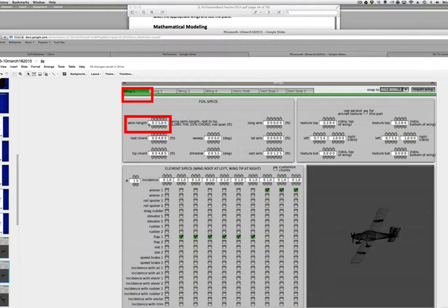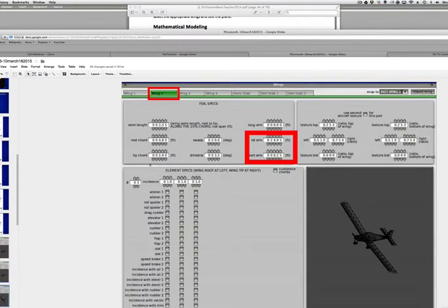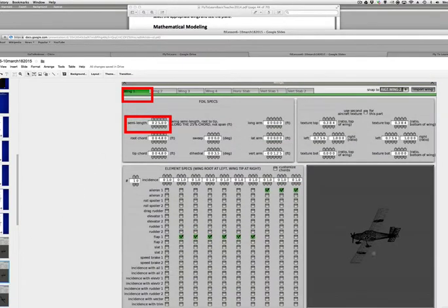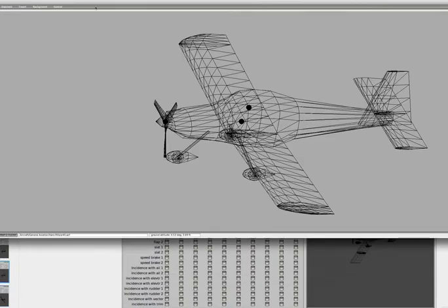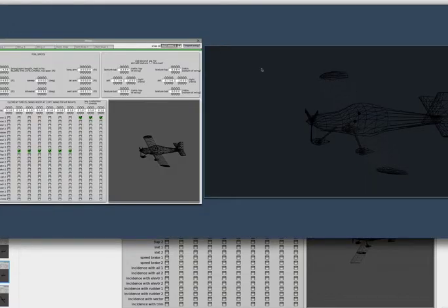So we're going to go into wing 1 and change some things, and then the wing 2. Wing 2 are the wing tips in this particular model. Wing 1 is the main wing, all right? So let me go here. Let me bring it up so we can build this. So everybody watch. Now watch this. I'm going to go into standard. I'm going to go into wings. There's wing 1. Notice the semi-length is 14.136.